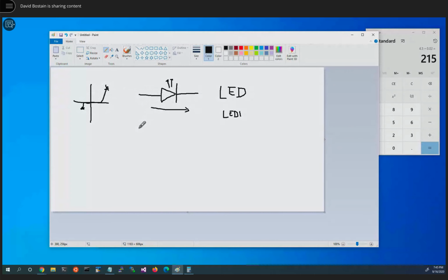Now, in a particular problem, if I don't give you some design requirements, let's have our first set of requirements. The first requirement is that if I don't tell you otherwise, this point right here where the LED turns on is at 2.1 volts. We call that VF, V forward. It's the forward voltage across the diode when it's reached the point where it's turning on.